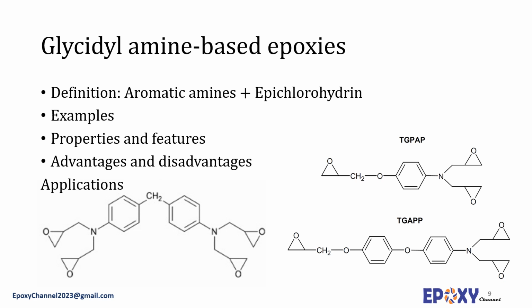As the functionality increases, the cross-linking density would be higher and therefore the mechanical performance of the cured product significantly improved. Regarding the advantages and disadvantages associated with these systems, we should imply that due to their outstanding thermal stability, good adhesion strength, and low viscosity, glycidyl amine epoxy resins are increasingly used in the manufacture of high-performance composites, adhesives, and coatings, and find several applications in the aerospace and aircraft industries.